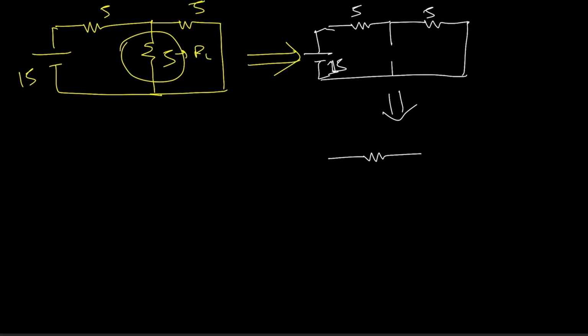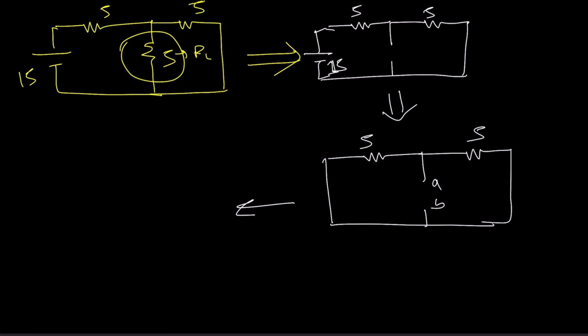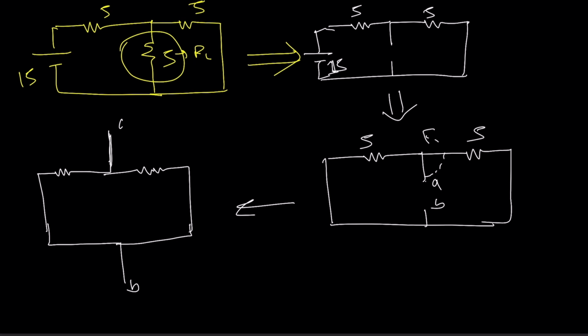Then replace it with the short circuit. Now we need to calculate the value of this equivalent resistance of this circuit. Okay. So if we just move this one to this position, then we can draw like this. Just draw the A terminal in above. Okay. Now this is 5 ohm here and this is 5 ohm here. Here I draw the B in the bottom.